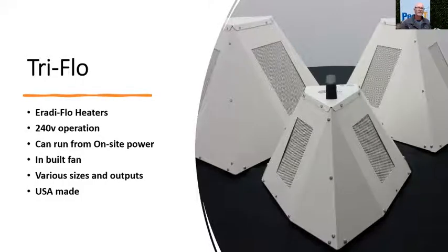The only downside of using 240 volts is that it will take longer to heat the room in a lot of cases. In a typical hotel room setup, you'll have about 9 kilowatts of power at your disposal. When you move into 3-phase power, you'll probably have about 18 kilowatts of power at your disposal.